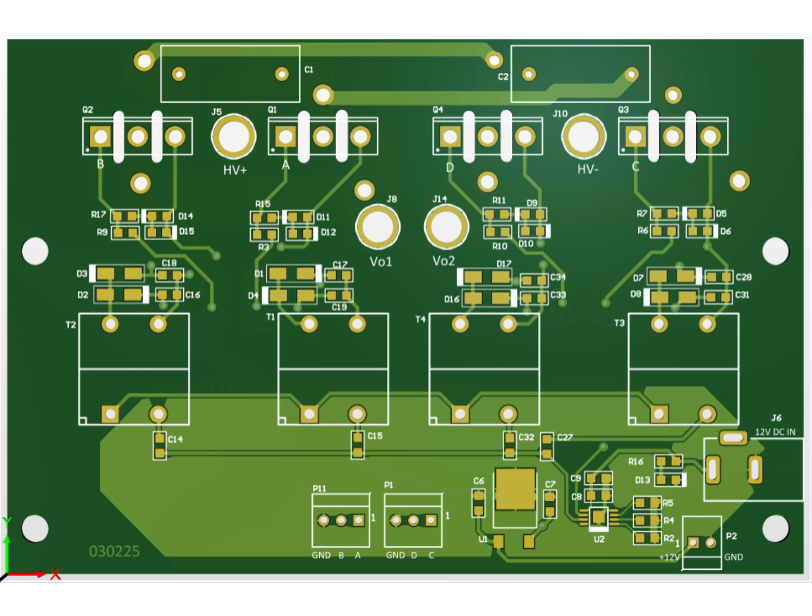You can also see that the DC bus decoupling capacitors are placed very close to each half bridge. This is intentional and critical. It minimizes the high-frequency current loop area and significantly reduces switching noise.